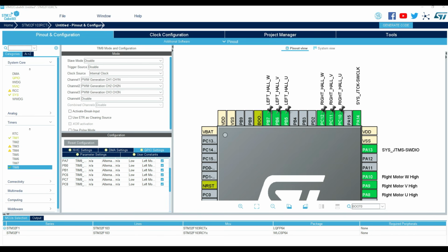Without Hall sensors, the motor does not know its position, and cannot start or has a jerky start. We can also use it for measuring the speed. If you need some more information, why 3 Halls per motor: this is for the 6 positions, to know exactly when to switch the phases on and off. And timer 4 and timer 3, these are internally connected.